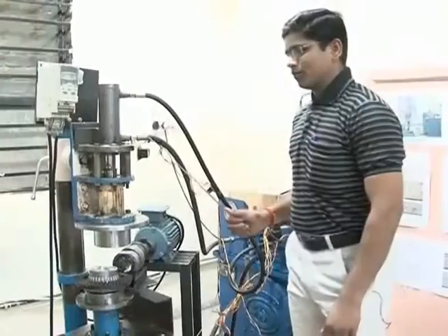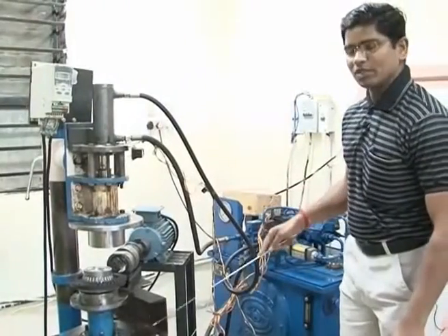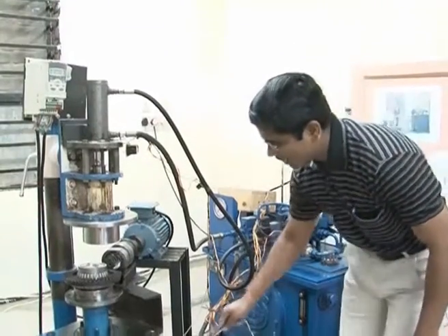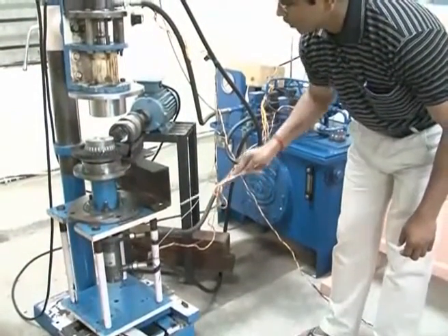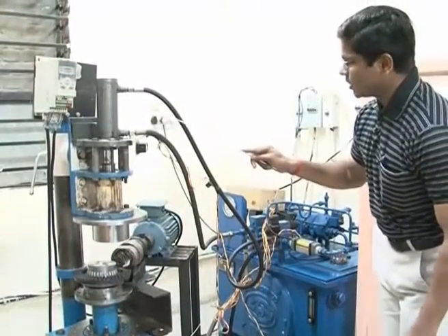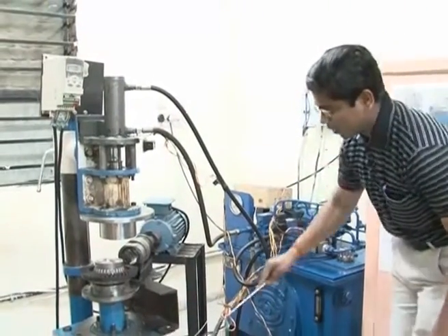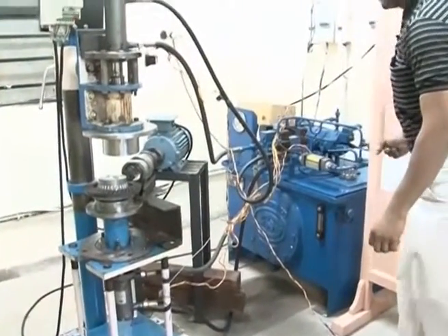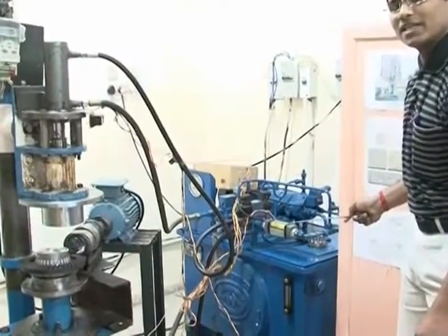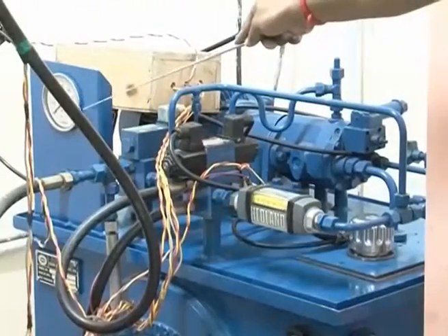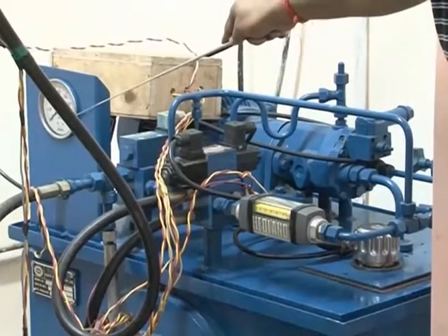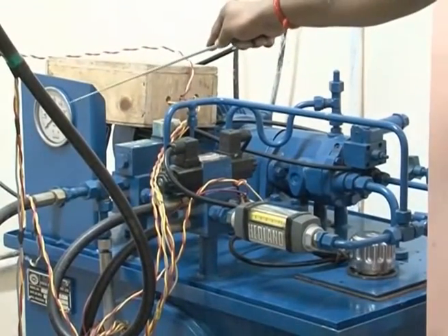Coming to the abrasive flow machine, it is a double acting abrasive flow finishing process. You have an upper hydraulic cylinder and a lower hydraulic cylinder, and a lower medium cylinder and an upper medium cylinder. These top and bottom hydraulics are controlled by a hydraulic power pack. This is the hydraulic power pack, where you can set the extrusion pressure. You can go to a maximum extrusion pressure of about 140 bar, that means 14 megapascal.